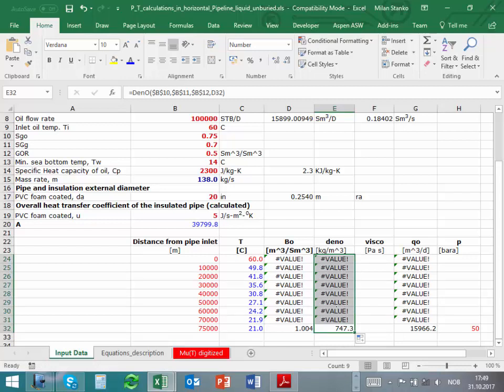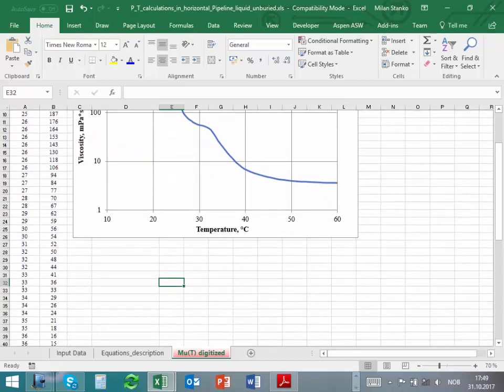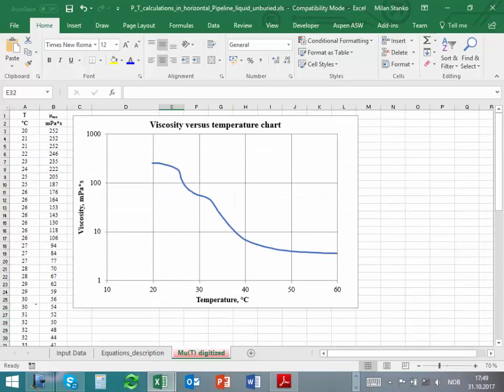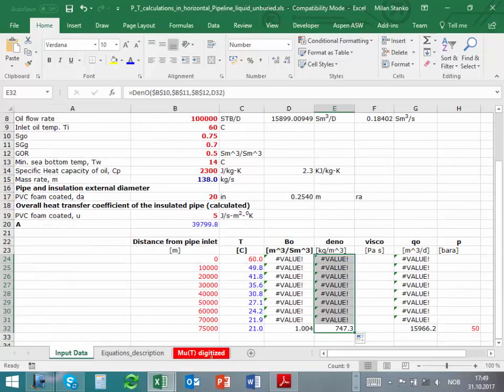So now I still need one more thing for the pressure drop calculations, and that's the viscosity. Okay, and the viscosity, we're going to make an interpolation in this table. Actually, we have now, for example, 21, and we want to interpolate here and say, here you have 21.10, and here you have 20.53, and I want to interpolate between these two numbers. Okay? So for that, I also prepared a function for you that makes the interpolation automatically.